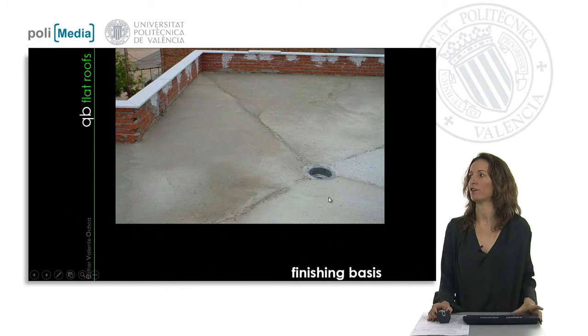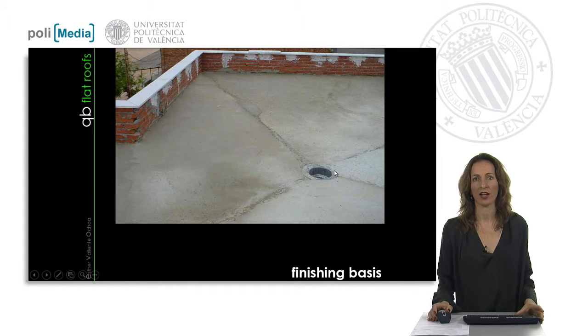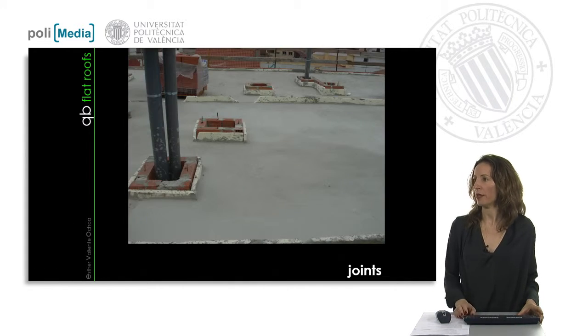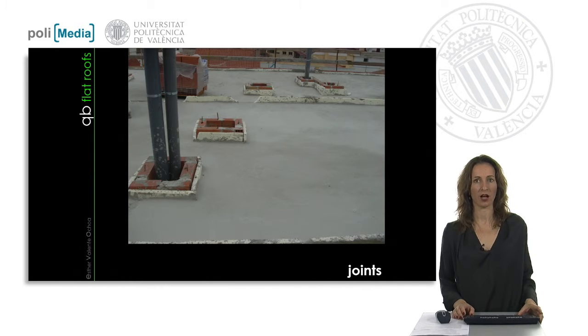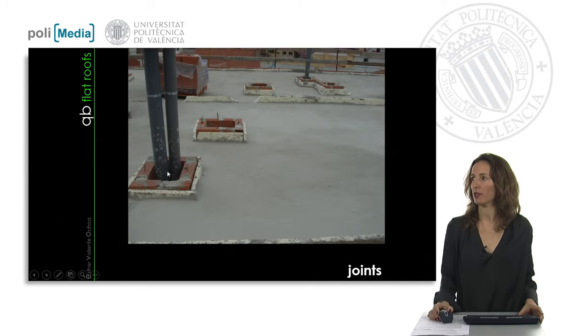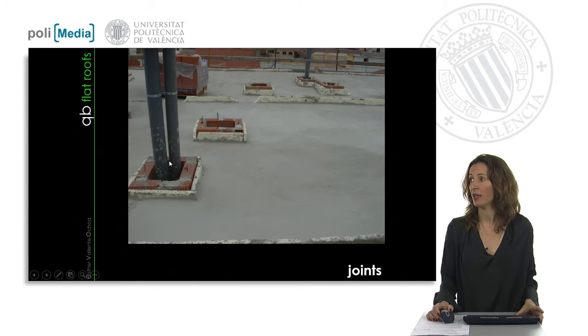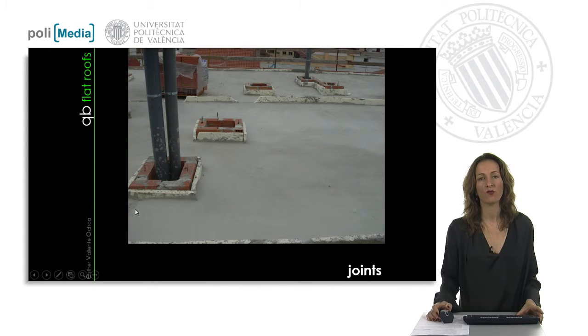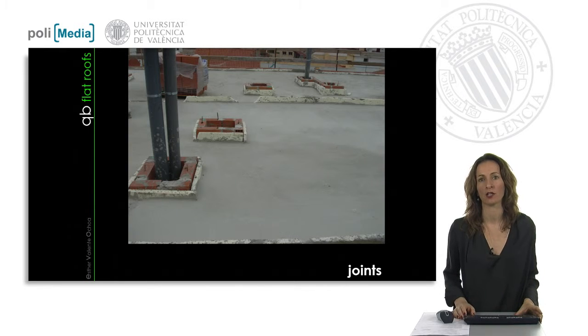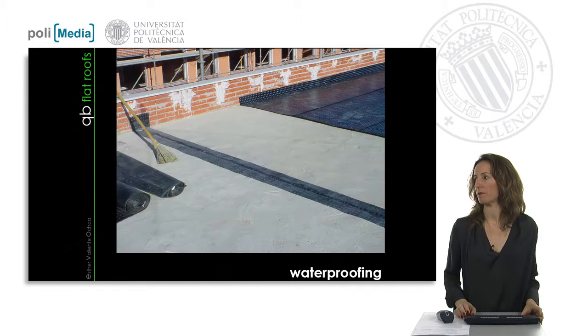At the time, in the finishing phase, we have all the drains very well protected and in use. The joints between the other building services also have to be checked. In this picture, we can see how the chimneys where different building services are going to run are protected with these polystyrene pieces that allow movement and will not crush the chimney and the elements inside the cover, between the pieces made from our mortars.